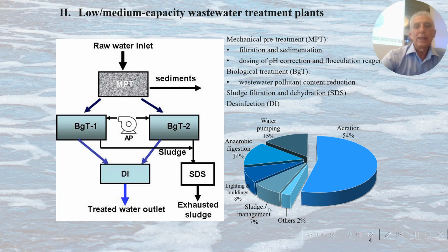First, we can observe here that the energy consumed for aeration in a treatment plant is about 60%. That means it's a lot of energy consumed by blowers to do tank aeration. To save energy, it is necessary to have a good control system and, if it's possible, optimized control.